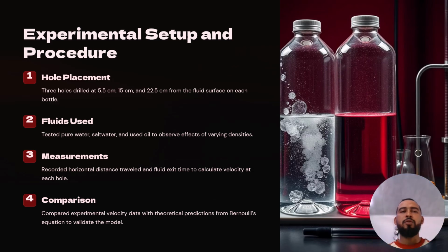In this work, the method was measuring time and horizontal distance for holes at 5.5, 15, and 22.5 centimeters. Results aligned with theory, though minor discrepancies occurred due to real-world factors like viscosity.